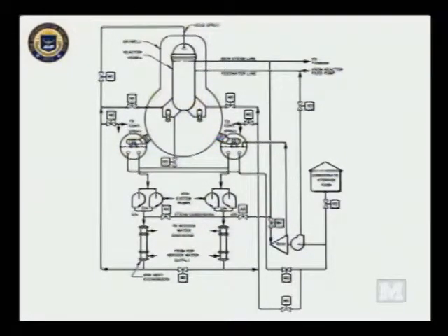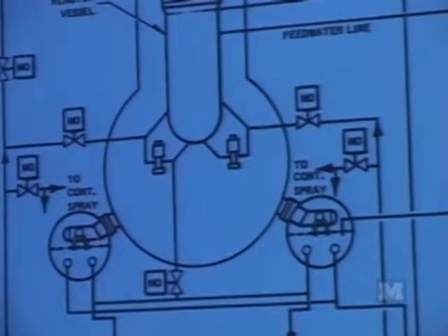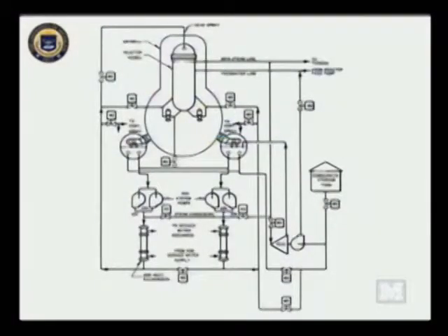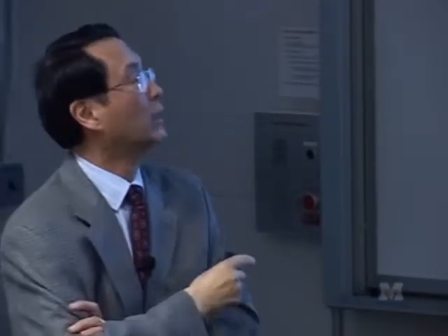So there was a relief valve, which is not shown here, was manually opened, and the hydrogen was vented into the space that's outside of primary containment, which means that space is inside the secondary containment concrete structure. And hydrogen ignited, if you will, chemically reacted with oxygen, air in the secondary containment space, and that knocked off the rooftop of Unit 1 and Unit 3, I believe, of the Fukushima plant. And that was the beginning of the deterioration of the event.